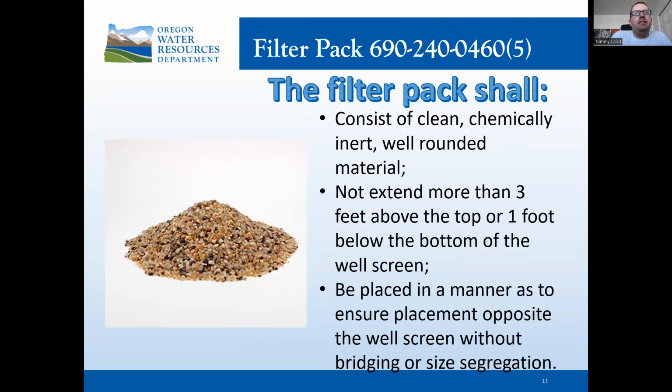The filter pack needs to consist of clean, chemically inert, well-rounded material. It shall not extend more than 3 feet above the top or 1 foot below the bottom of the well screen. It needs to be placed in a manner as to ensure the placement opposite the well screen is done without bridging or size segregation.